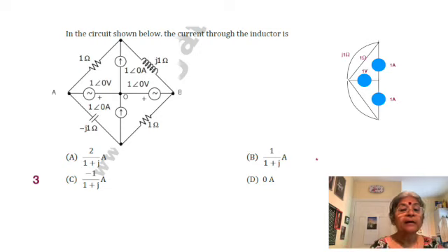It means that the outer 2 points, let me call them A and B, are at the same potential, so the circuit can be folded such that they are placed one above the other, and with respect to AB, O is at 1 angle 0. That is what is shown on the right hand side.